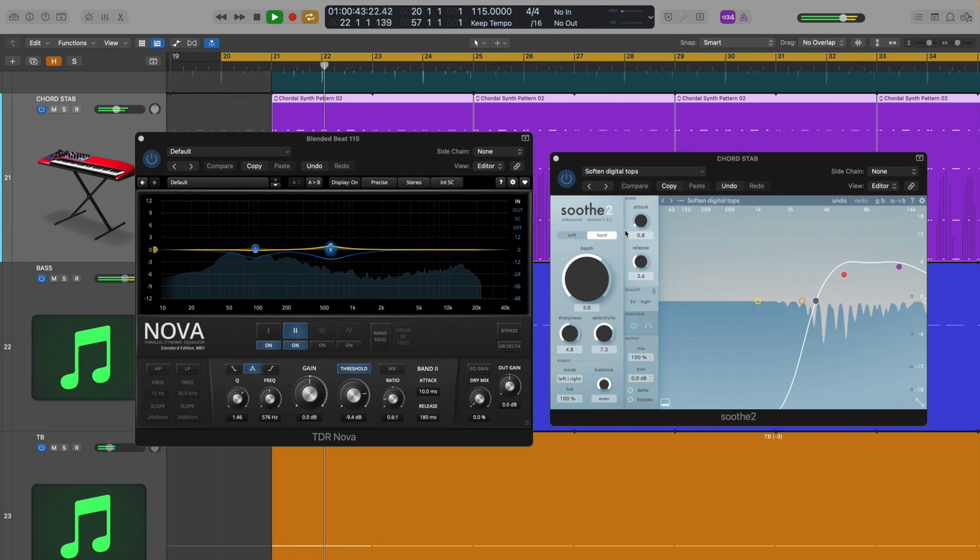In this tutorial, we're taking a look at dynamic EQ. There are times when neither EQ nor compression alone can deliver the shaping we require. Dynamic EQ is a focused process that combines EQ with compression or expansion, allowing us to make frequency-specific threshold-dependent changes. This is an incredibly powerful concept, as it means you're only processing the target frequencies when they reach a certain threshold. The rest of the time your signal is unchanged.